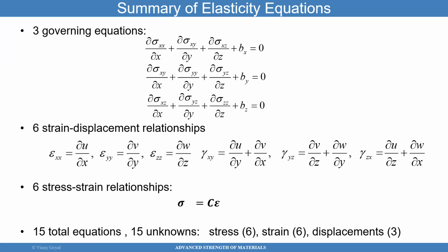Because that is the way you design systems. That's how you predict failure of a system. Where the stresses are the highest is where the problem areas could be. And so if I have very high stress in an area and I predict it's going to fail, perhaps what I want to do is increase the thickness in that zone so I can decrease the stress there. That's sort of what we're trying to achieve here.